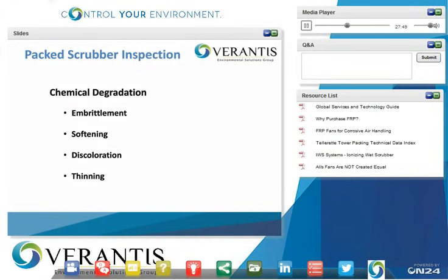Next possible reason for packing damage is chemical degradation: embrittlement, softening, discoloration, and thinning. For the basis of the discussion here, I'm going to use polypropylene as the material of construction. That's the most typical material of construction for corrosion-resistant packings. We offer other materials too, Kynar, CPVC, and some Teflon materials, but polypropylene, because it's the most economical, is the most widely used in the industry.